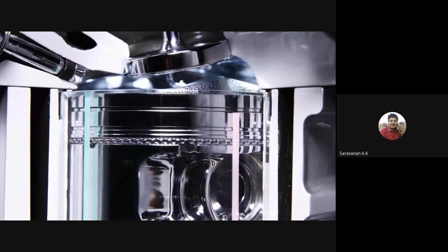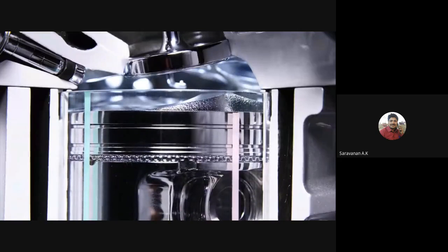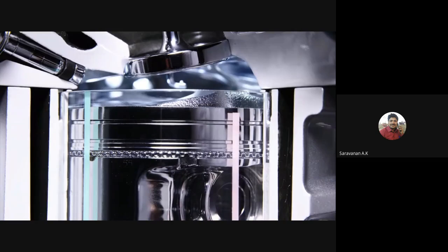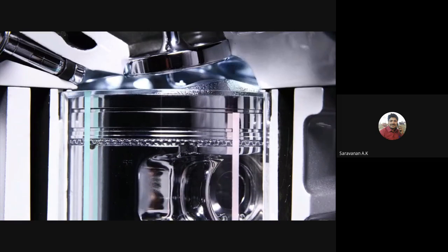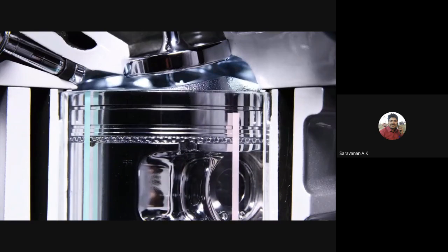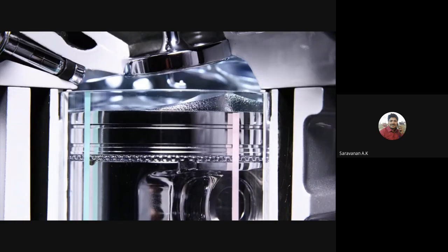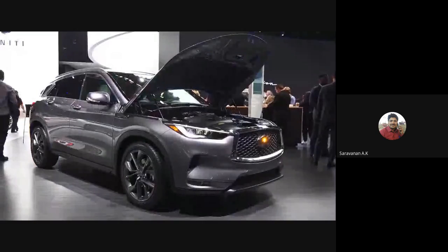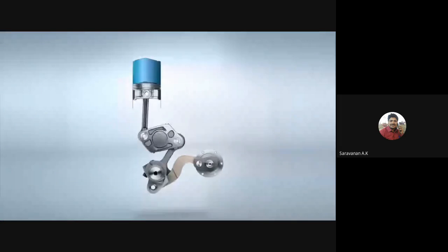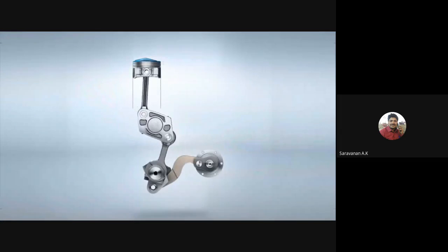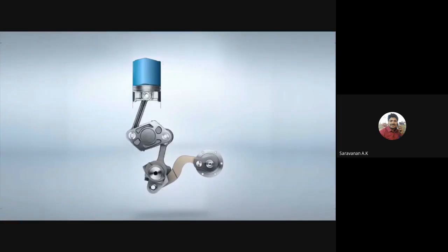Now, so far I've made it seem like the engine operates in two distinct modes, but in reality it's fully variable and can operate at any unique compression ratio between 8 to 1 and 14 to 1. Ultimately, the engine will choose the ideal compression ratio for the situation, depending on the driver's throttle input. If the driver is not asking for power, it will adjust the compression ratio to operate as efficiently as possible for the given gas pedal position.